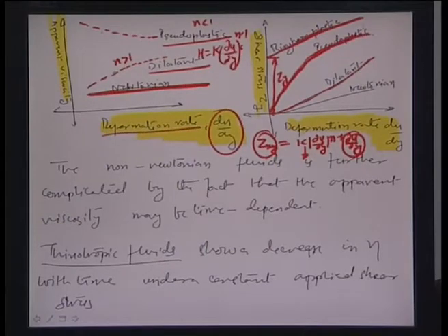And so it stabilizes to a certain value and then falls down beyond it, and in the case of a dilatant it is the opposite effect because there is an add on, and so the du by dy to the power n minus 1 component starts dominating after a while, and it further increases the shear stress value. In case of a Newtonian fluid though, as the viscosity is constant, we would expect a linear behavior between the shear stress tau y and the deformation rate du by dy.